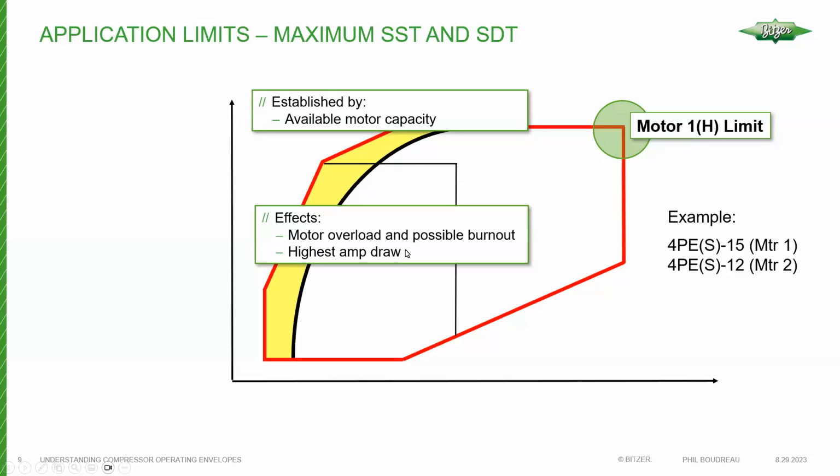Unfortunately, as you may know, motor burnouts can also result in an acid condition throughout the system. Acid really needs to be dealt with carefully, because future compressor replacements can have a short life if the acid is not totally cleaned up.